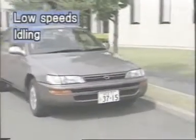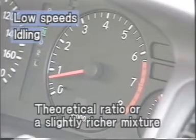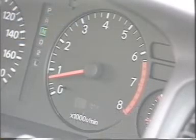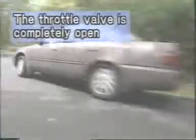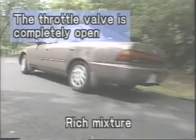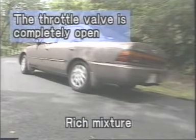When the engine is idling, or when the vehicle is traveling at low speeds, fuel and air do not mix well. Because of this, it is necessary to achieve the theoretical ratio, or a slightly richer mixture. A greater ratio of fuel to air is necessary to obtain the needed power when climbing hills, or other times when the throttle valve is opened wide.